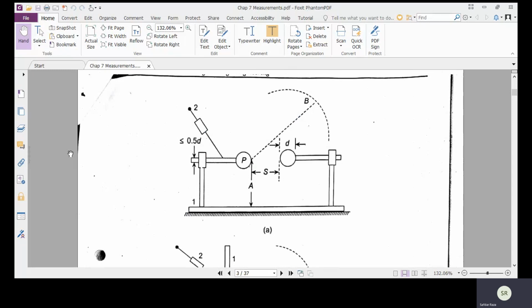In case of horizontal arrangement, the height of the sparking point on the sphere above the horizontal plane must be within the given limits related to the sphere diameter. Here again the point is that the height of the sparking point should be above the ground, because definitely at this level the testing engineer, the measuring engineer, or an electrical engineer is there.